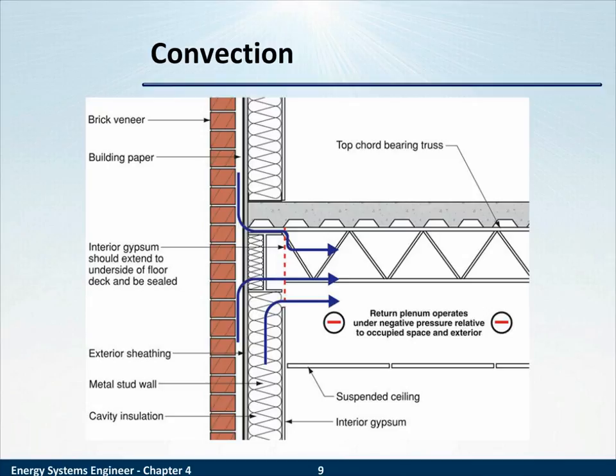But this picture of convective heat transfer shows a little more insidious heat transfer. If there's a gap in a window or a gap in a door, you'll feel it. But what if there's a collection of small gaps that you can't feel and you can't see because they're between the outside facade, in this case maybe a brick veneer, and the exterior sheathing or cavity? There's a little gap there, and the gap in its area is huge. The gaps themselves are small, so a lot of these small gaps can create a substantial unintended influx of outside